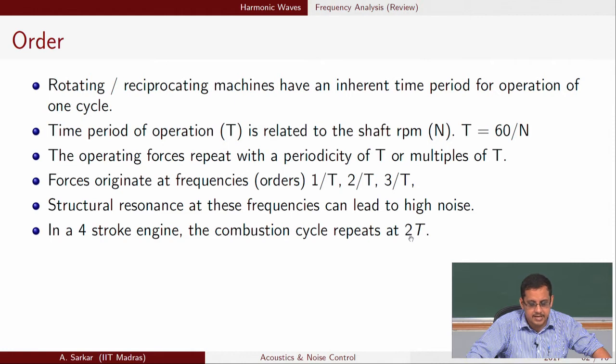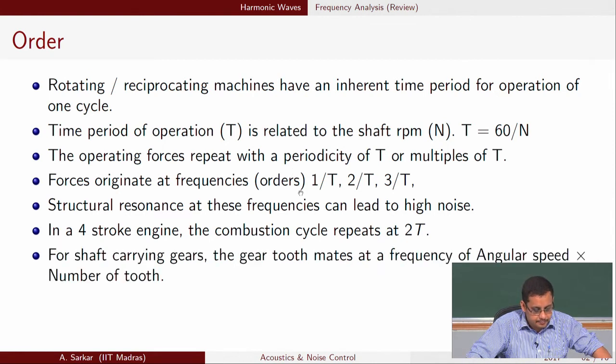Just as I said, the difference in a 4 stroke engine as compared to the others is that the combustion cycle will repeat with 2T, and therefore you will have 1 by 2T as the fundamental frequency, and all integer multiples of this fundamental frequency will be present in any noise and vibration signal.